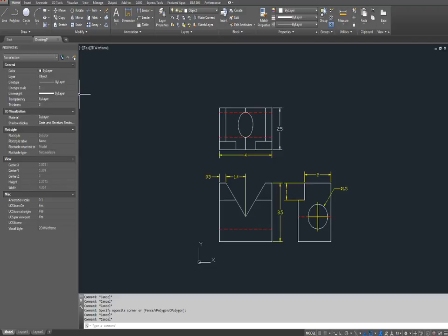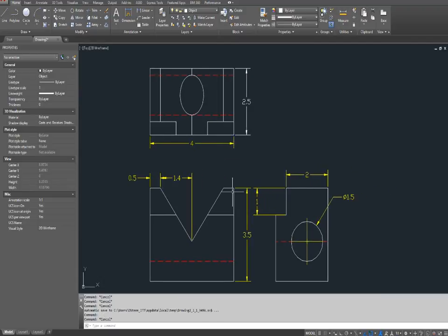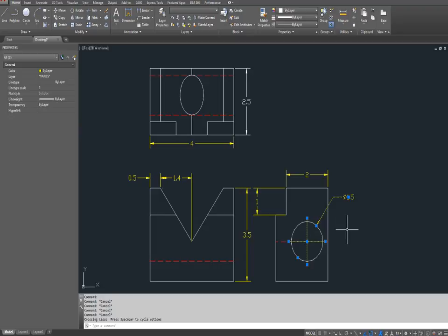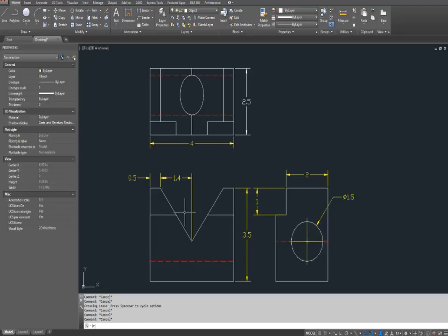So you can learn all your tools for your dimensions from the properties. Select the properties. Last thing, I'm going to be looking to see if you did the LT scale right. So LT scale is the line type scale for the entire drawing. Right now it's set to 1. I'm going to set it to 0.75. And you can see all my hidden lines got shorter and my center line showed. I like to draw my own center lines. This will need a center line too, and there needs to be a center line running through the whole thing.